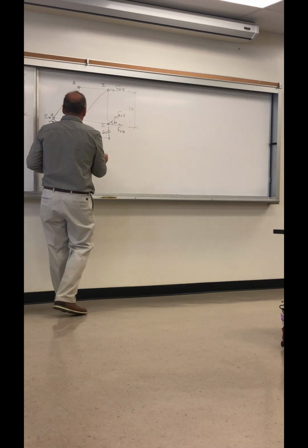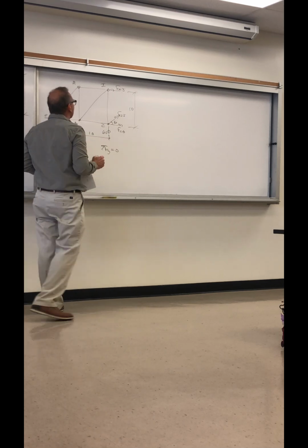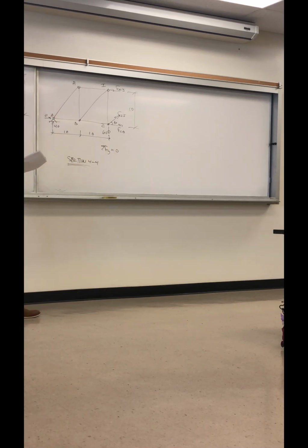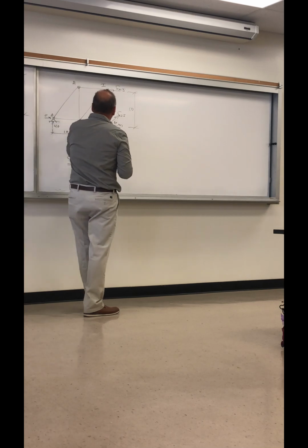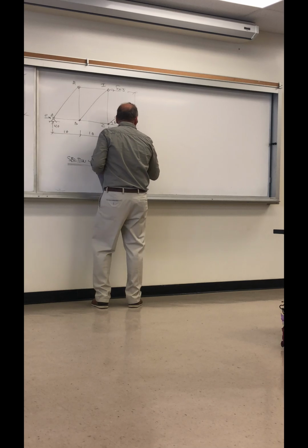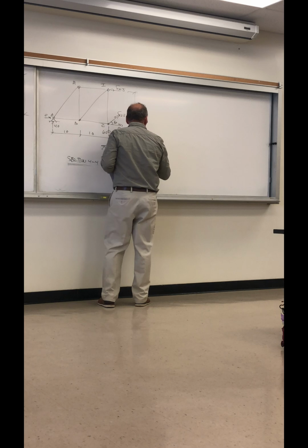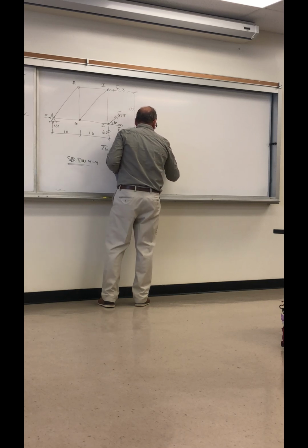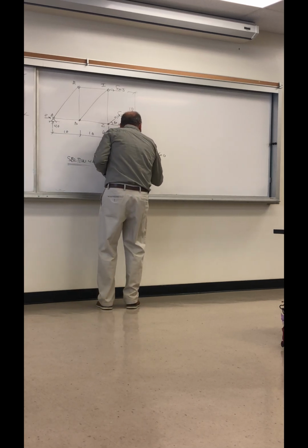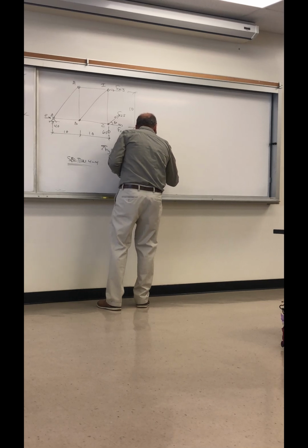So summation of forces in the y is 0. We'll solve for F of CJ, but it's at an angle. Remember we cut through, right? So we have to take the component of it. And we have to include the 60. So we have F of CJ multiplied by the sine of theta plus 40 equals 60. So F of CJ equals 28.3 in tension.